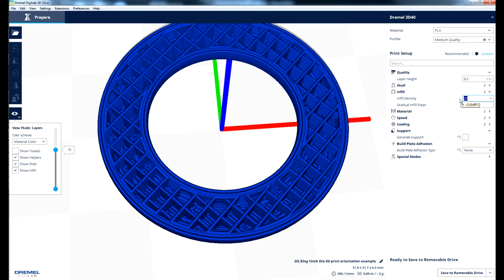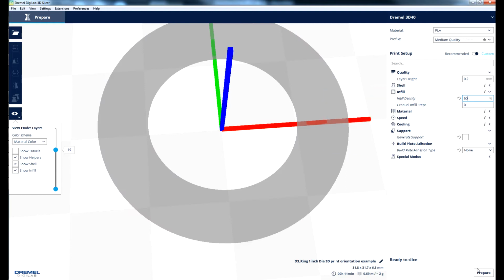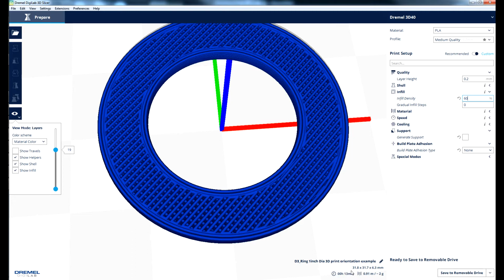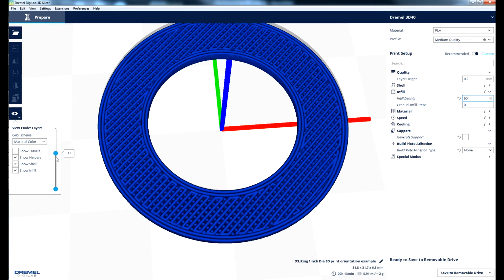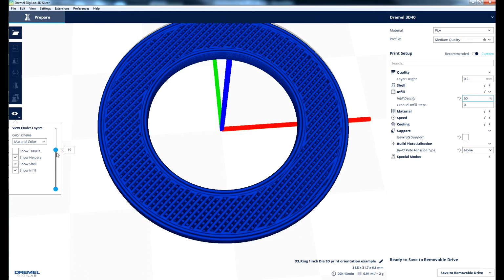Infill does have a significant influence on a part's strength, but with limitations. Remember, we can never exceed the strength properties of the filament. A mindful infill coupled with thoughtful part orientation are the best assets for strong parts.